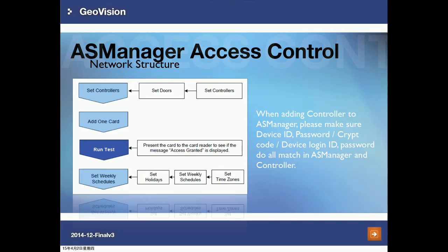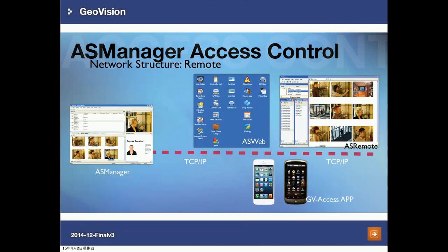One thing to take note of when adding the AS controller to ASManager: you have to make sure that the device ID, password, the crypto key, and the device login ID and password are all matching in ASManager and the AS controller.